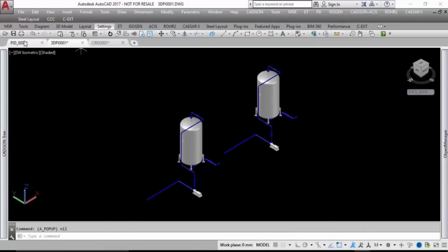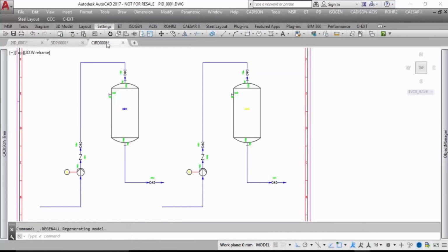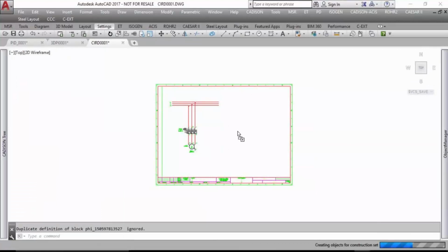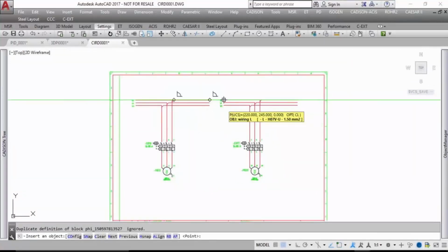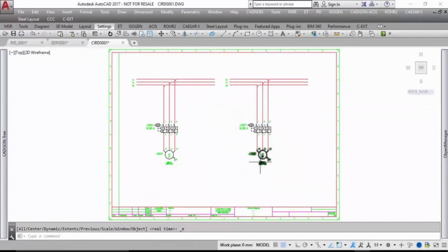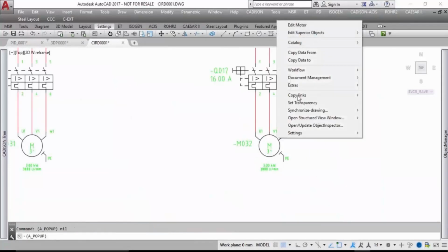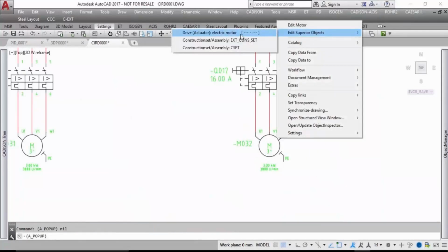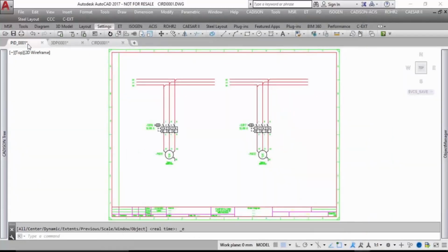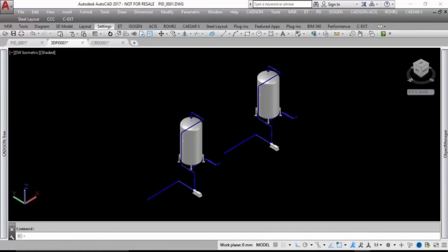This means that users or companies can keep integrated standard designs in the construction set object of the object manager, and then every time such standard packages are required, it can be directly dragged and dropped from the object manager of the CADISON designer. This is a very interesting functionality for the companies who work mostly with standards.